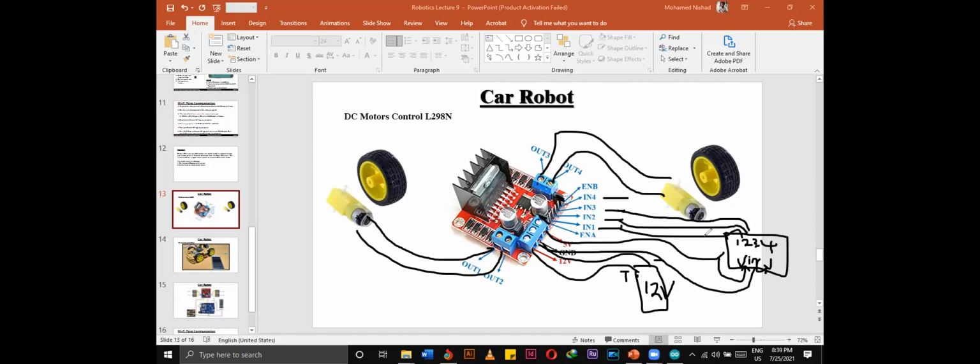Accordingly, you can connect, but you have to be aware that the first pin is for RX, and the 0th pin is for TX, right? So you have to be aware of that. So you can alternatively connect the 2, 3, 4, and 5th pins, right? So you can connect these things, and you can have the Bluetooth module. The Arduino has a 5 voltage and ground also. You can obtain a 5 voltage and give it to the Bluetooth module. In the ground, you can obtain and connect it to the Bluetooth module.